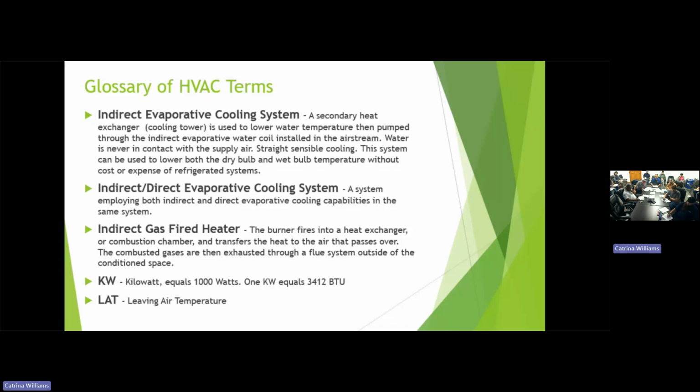Indirect fired, gas-fired heaters. Now we have those in a stainless steel heat exchanger or some sort of a combustion chamber. That's what we pass the air over, and then that heats the air. So this is another version of a heat exchanger, transferring heat. Then the combustion gases are exhausted through a flue system and outside the conditioned space. You don't want them being put back in because you do have CO and some bad stuff in there you don't want to be breathing.